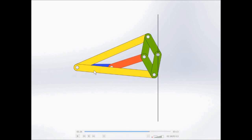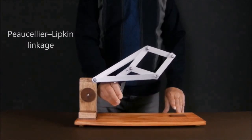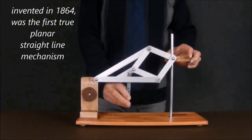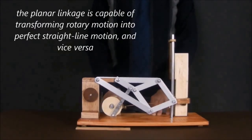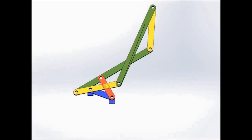Then the other condition: these yellow links are equal in length. Then this red link and blue link, you can see, is a fixed link. From this point to this point is the blue link. This is a moving link. So this blue link and red link are both equal. These are the conditions for the Peaucellier mechanism. So this is a real, actual mechanism. You can see that this end can move only in a straight line. We don't want to constrain it, but since it is a free end, it will move only in that straight line.